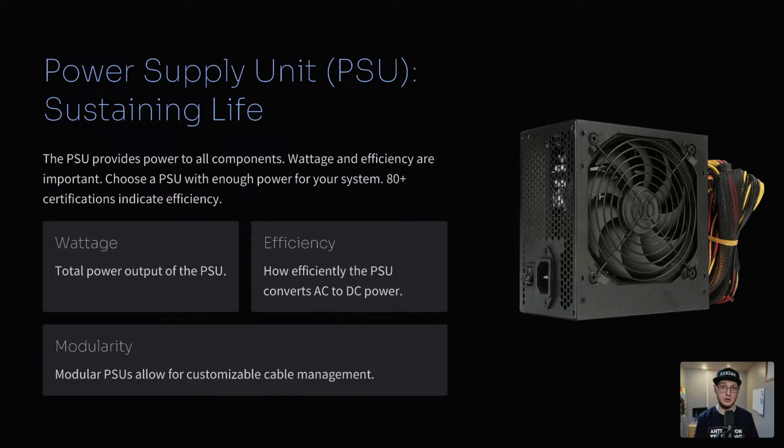Now, some of the big things when you're picking out the power supply is figuring out what kind of wattage do you need. That's when you have to look at the fans that you have, the processor that you have. You have to take a look at how much wattage range you're going to be utilizing, especially with the graphics card, which makes a big difference as well. And that's another reason why using something like that PC parts builder is helpful, because it will give you a recommended power supply. And you always want to overshoot that a little bit as well.